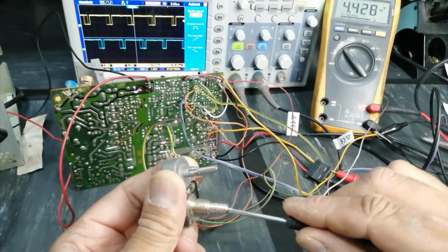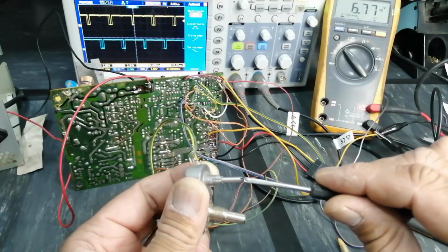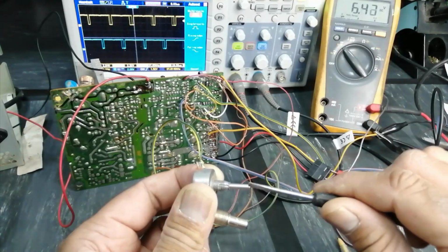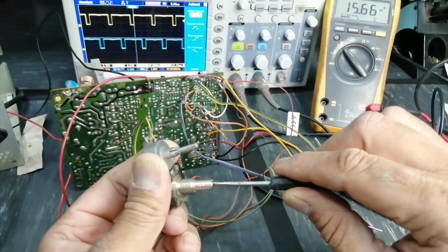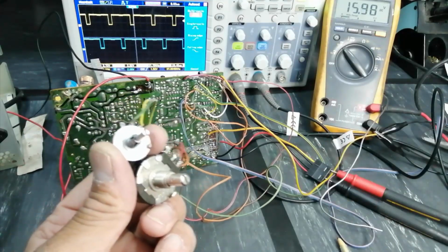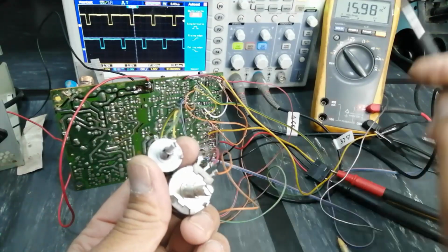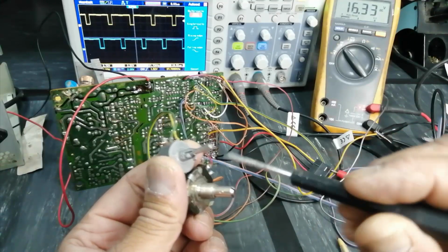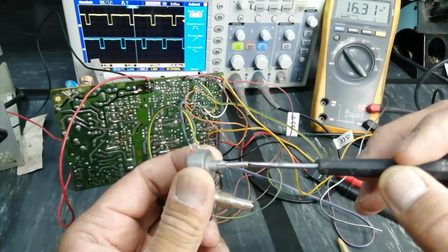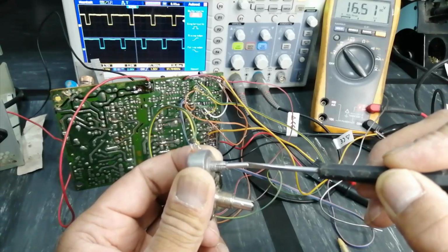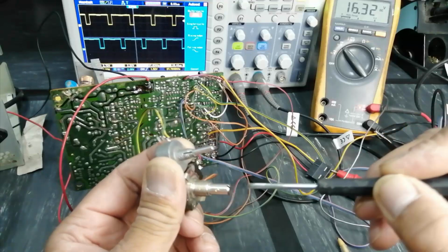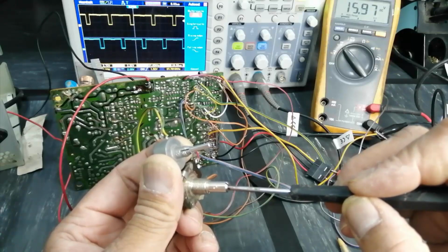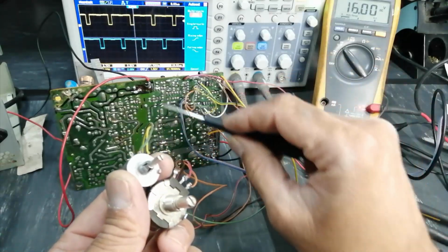The basic idea of this video is to disable the sense line. Suppose I need 16 volt. What do we have to do? 16 volt. I adjusted this potentiometer, and we can fine adjust from this potentiometer as well. We can put these knobs in the panel and we can use it as an adjustable power supply.